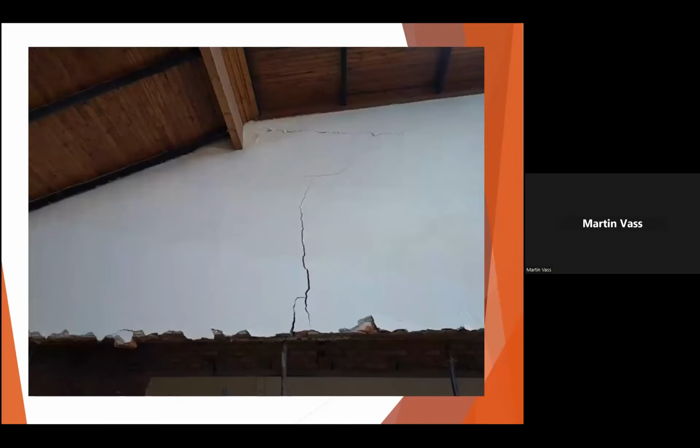As they removed the brickwork, the brickwork above started to fail. It started to crack. And that's what we would expect, because then load slowly comes onto the steel truss.